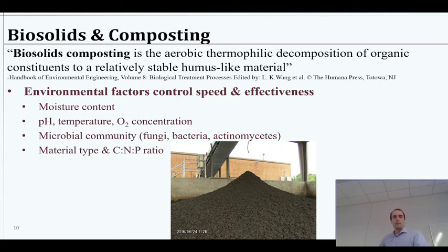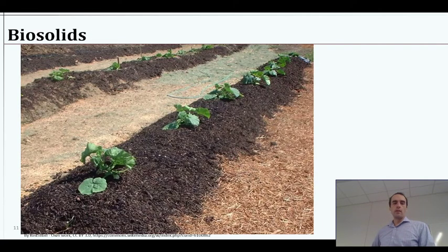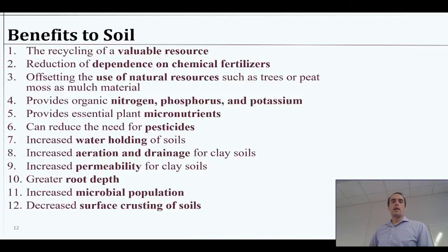Okay, so biosolids. It's going to be a little bit like making topsoil out of wastewater solids. So it'll end up being applied something like this, or perhaps sprayed over land. A lot of benefits, potentially. Fertilizer, potentially improve soil quality in terms of aeration, how well it holds water, also how well it drains water if you have clay type soils. So all the things you'd get with adding some sort of humus topsoil type of stuff.